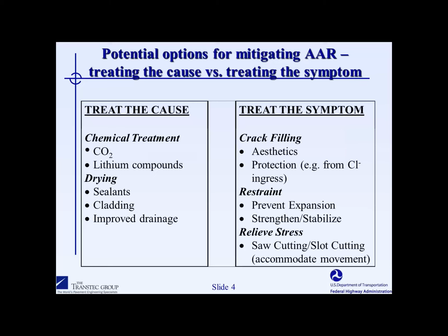So this is why we're quite interested in lithium as a technology. And essentially what lithium has the ability to do is to react with the ASR gel and essentially make it so that it no longer expands or expands much less. So we'll show some field trials involved with lithium.